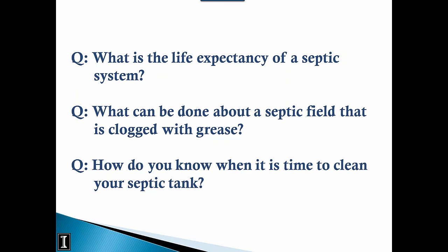Okay. I think the first thing you've got to make sure is, is it definitely grease that's clogging this field, or is it the water table is up above where the septic effluent is coming out of the leach field? There's no way to fix that, other than to put a new leach field in. You can even bring in clean material to mound it up above where the water table is. But that's your first thing, make sure, is it definitely grease?